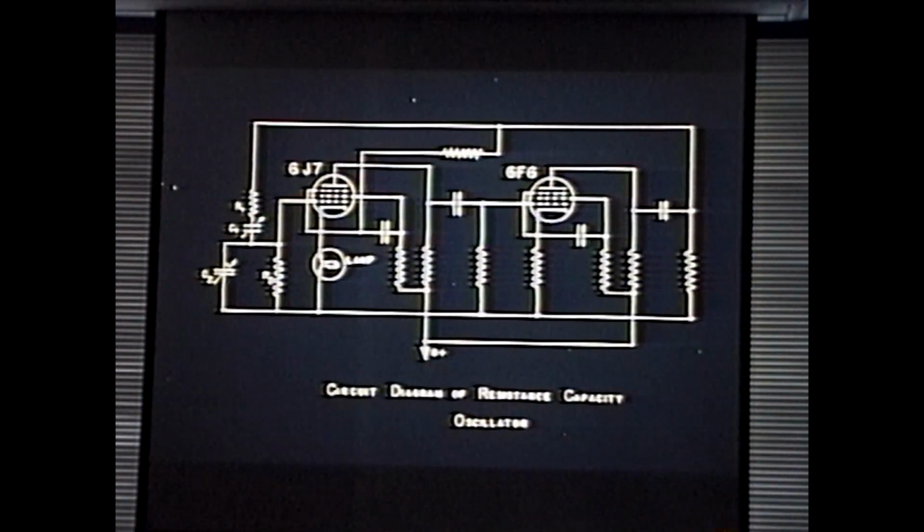This is an example of things you'll never find in a book. From a lamp sensitivity point, the most sensitive part of the lamp, where you get the best gain control action, is just below the point where the lamp starts to glow. Because once the lamp starts to glow, that's pure emission, and you don't want that. Okay? So you're right, he had to pick his lamp very carefully.